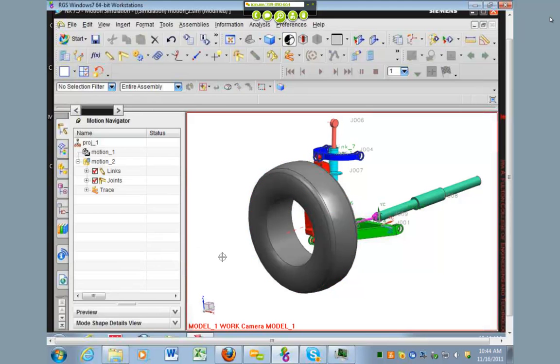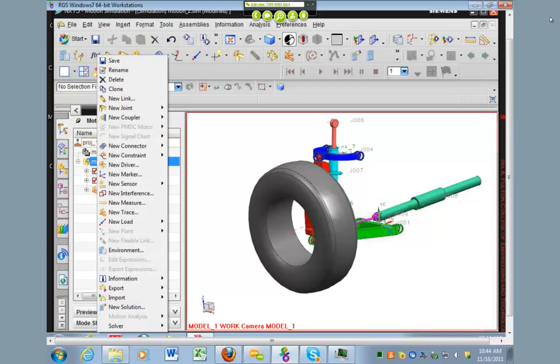So we're going to set up an articulation. We're going to apply step values to the joints with the motion. So we're going to tell it to step a certain number one way and the other way. So we're going to create a new articulation solution. Just like we did in FEA, you right click and say new solution.